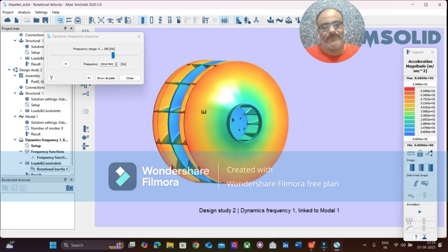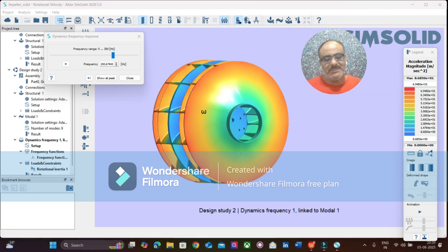Now it has become 2.5 G, or about 5 G at certain time, and then it has become 12 G at some point of time. So there is a dynamic variation of G force, and all these G forces are going to contribute onto the screws. Every screw is connected to the electronic modules within the cockpit. Those screws are supposed to be sustaining these G forces or the shock loads.